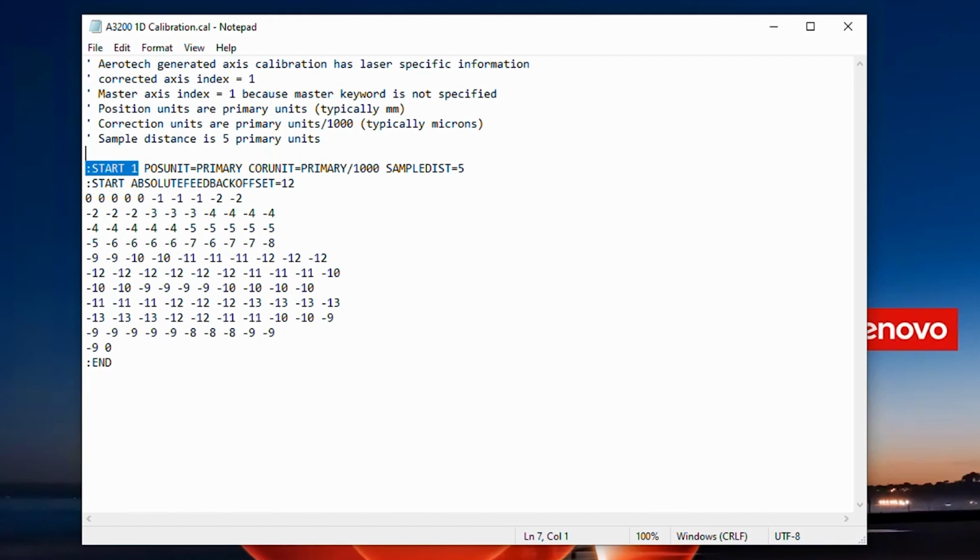Most often, the axes in a parameter file start counting at 0 for the first axis, so we don't want you to be confused when modifying the calibration file since the calibration file counts differently. So if you were determining which axes actually correspond in the parameter file to this in the calibration file, just know that the first axis starts counting at 1, the second axis at 2, and so on.